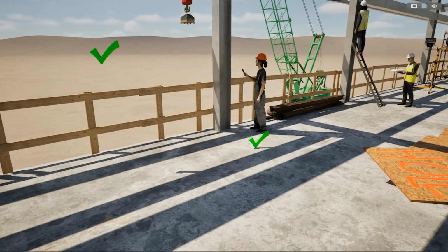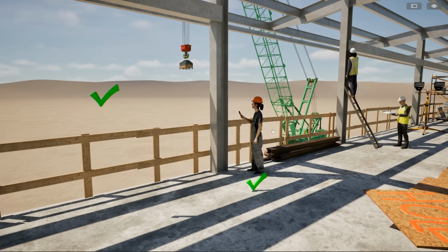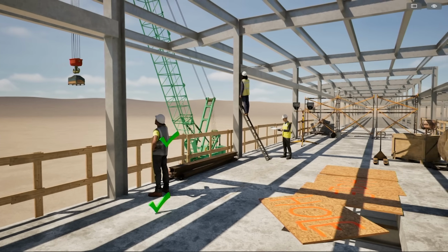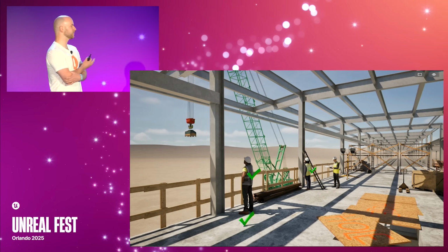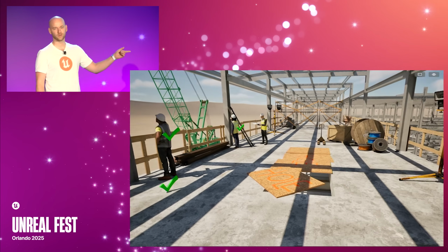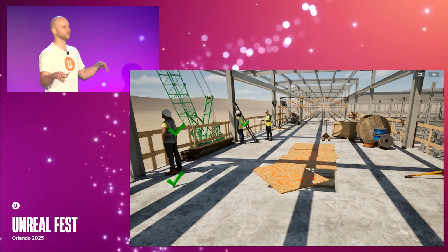And this gentleman has a hard hat on, but because there's heavy equipment around, we probably need some better high-vis shirts on. And then the guy on the ladder, of course, there's too many things wrong there. He's more than 6 feet off the ground. He needs the fall arrest. He's on the top 2 rungs of the ladder. We'll just get him off of that for now and figure it out later. The scariest thing to me is the hole in the ground, so we'll barricade that and make sure nobody falls in.